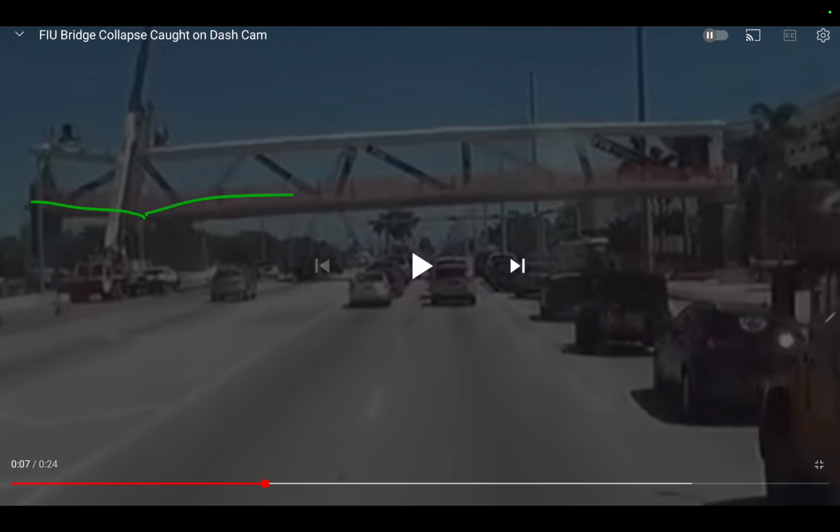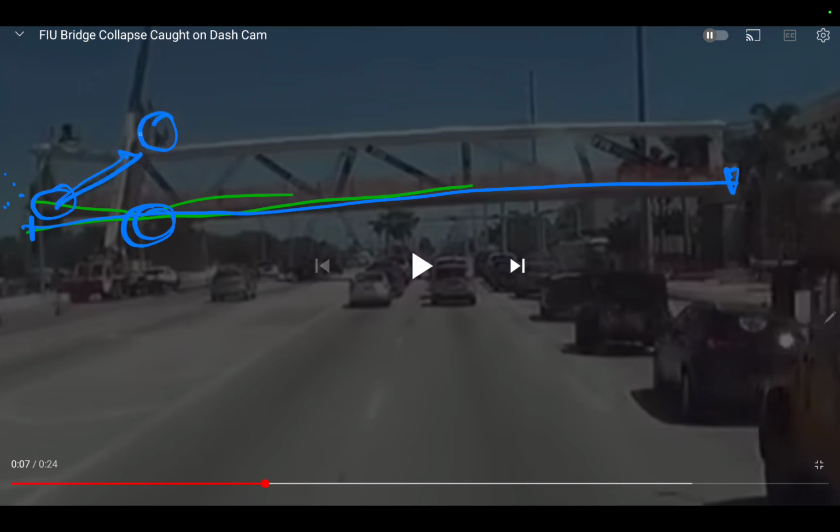From the dead load of the structure and what I believe the post-tensioning acting like a bar, failing right where you see it failed. They have it initially starting here, sliding off. The video does not show that. They say, well, you see some ejection. All right. Well, this can't move. This can't extend. This bar, these guys were just putting post-tensioning in this bar. This can't extend with a bar in it. It'll make itself longer. It can't do that. And there's a nodal down there anyway, some steel there.